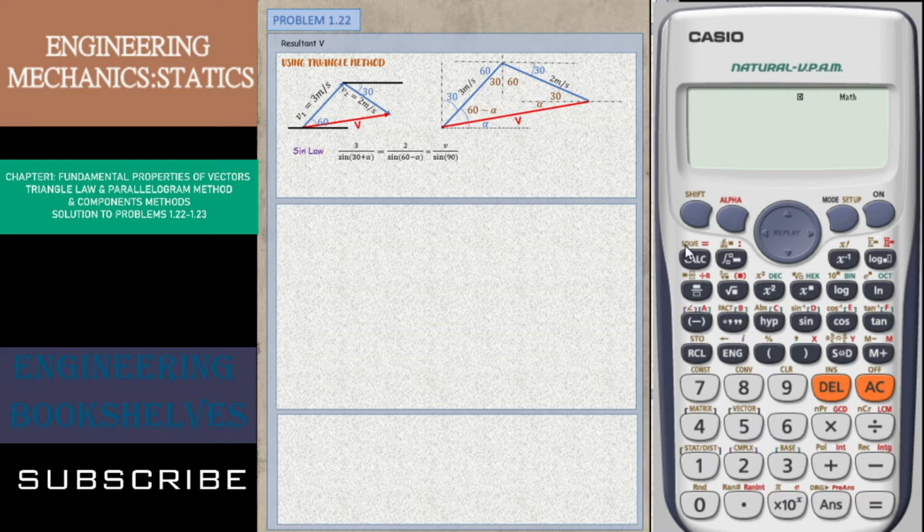Using our calculator, we can solve first for alpha: 3 over sine 30 plus alpha equals 2 over sine 60 minus alpha. Of course, we should set the value of x to be less than 60 degrees, so let's say it is about 30, for example. So the angle will be 26.31 degrees.